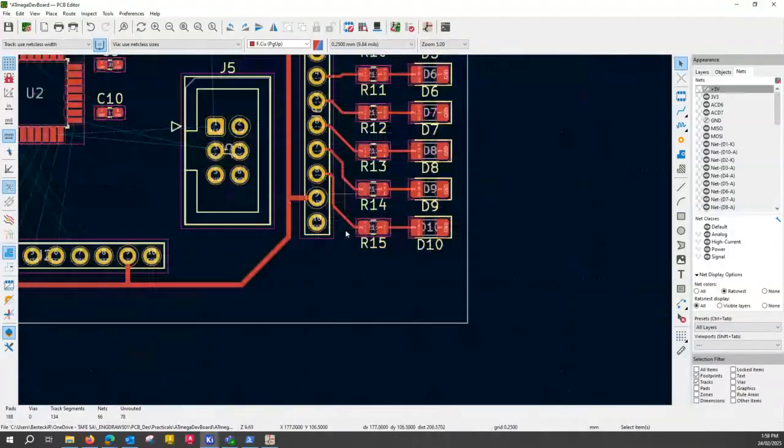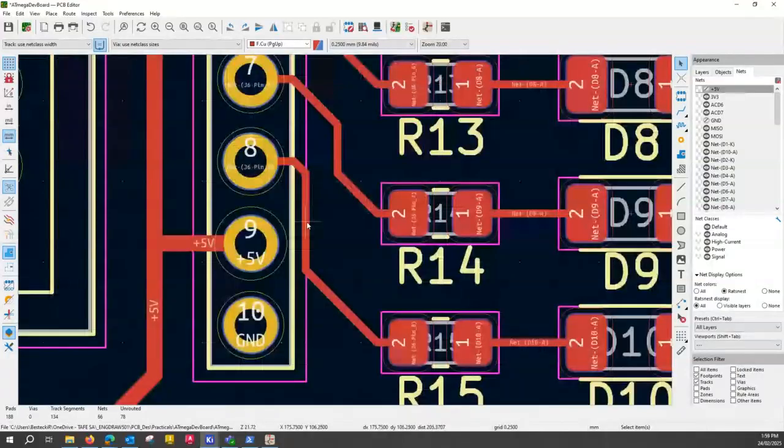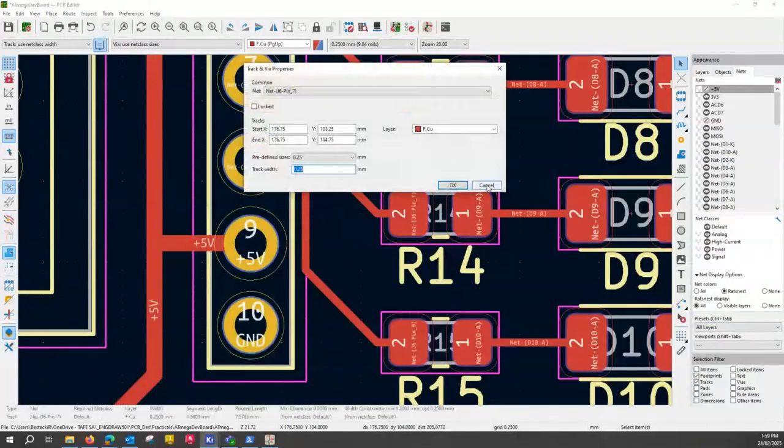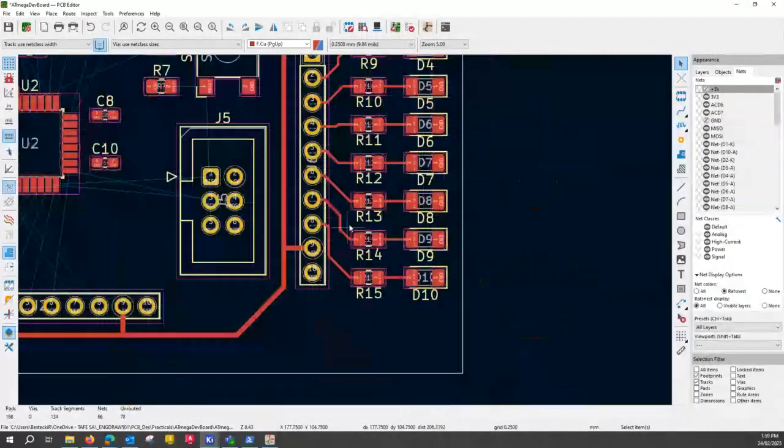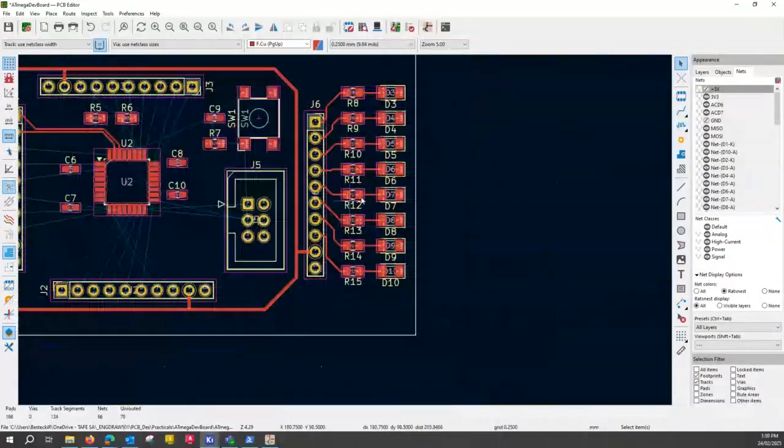Okay. I can either leave those gaps bigger so the ground plane floods through it, which is probably a good idea here. We still have reasonable clearance here to 5 volts. You can move it aside a little bit if you want to. We can sort of adjust. Oh, I double click too quickly, but I'll just leave some bigger gaps to make sure that my ground plane floods through in between those tracks. So this is it pretty much. This side is done.